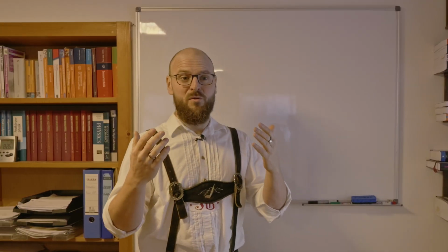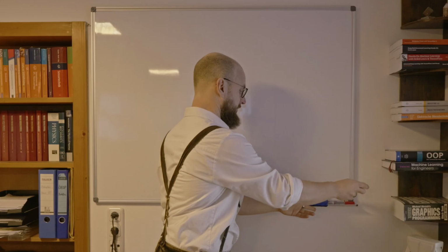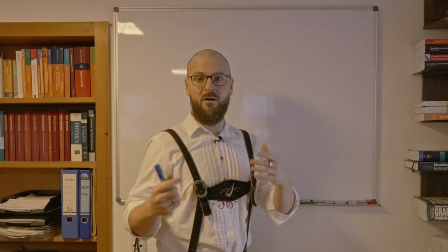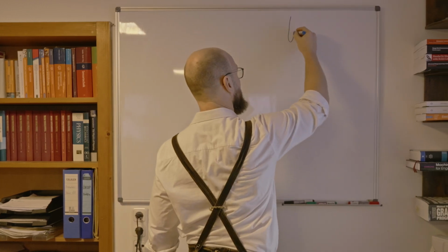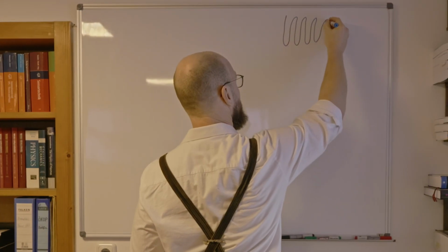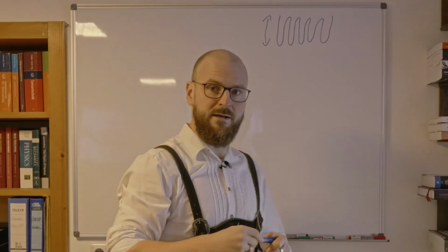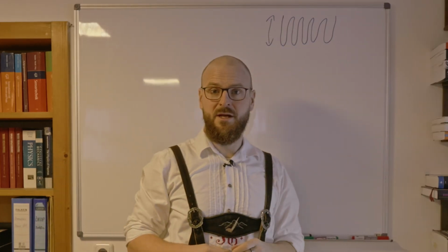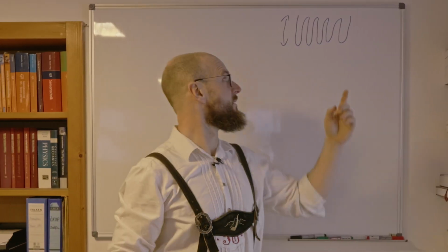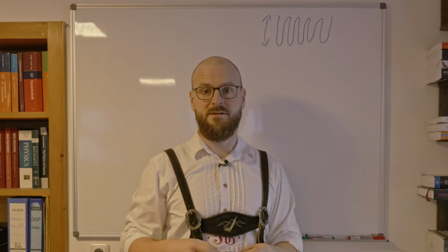And now, taking that idea and bringing it to some more usable way of deriving distances and length from that behavior is just to do something like meandering structures which are stretched and compressed in the way of the wire. And that is more or less a strain gauge. Meaning we are stretching it, the resistance rises, we are compressing it, the resistance is going down.